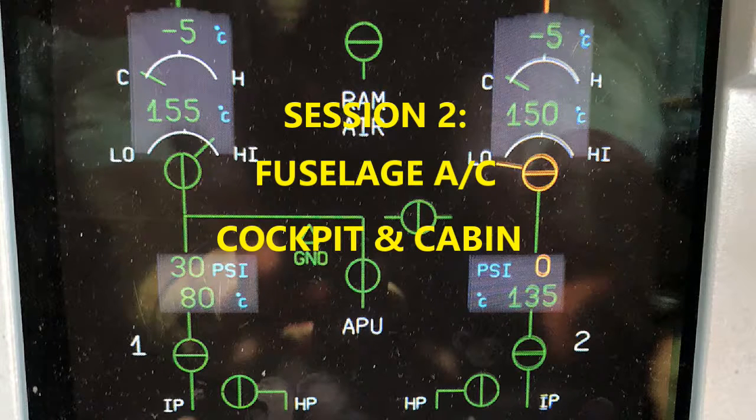Let's go over a little bit more on the pressurization of the cabin. There are interfaces, so I just want you to hear it verbally so you can have some familiarity with them. You have ADARUs, your FMGS, and your EIU interface, along with your landing gear CIU. Those give discrete signals for the flight/ground status that are sent to the cabin pressure controllers. So those are your interfaces. And of course, the monitoring system, we have that.